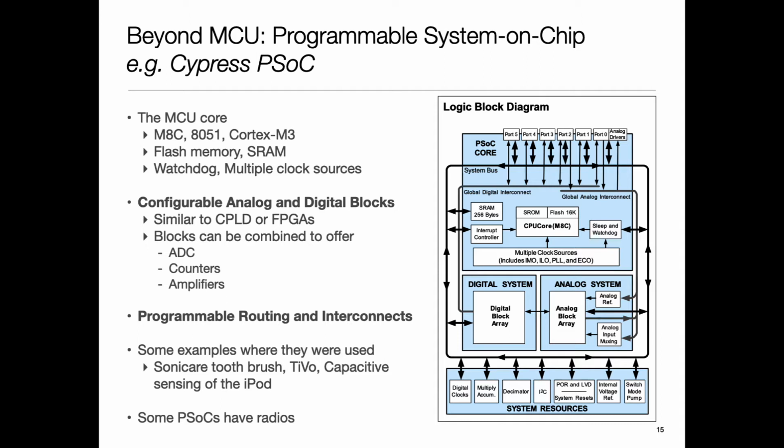Some companies make chips which have both these components. Firstly, the big FPGA companies like Xilinx have FPGAs which have hard processor cores. That is, there is a part of the chip where you actually just have a processor sitting, and the idea is that now you can make a whole system where you have a processor and you have the glue logic and accelerators and things like that surrounding it. At the low end, there are companies like Cypress who do the same thing, and sometimes they even have analog components. So literally everything that you might imagine in a system just sits on a single piece of silicon and works off it.